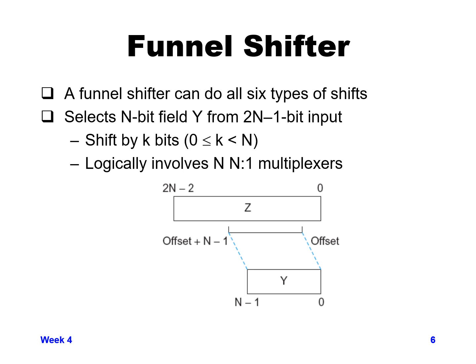So if we had a 4-bit number that we were trying to shift, we would need 4 to 1 multiplexers to get any value of shifting between greater than or equal to 0 and less than 4 shift.